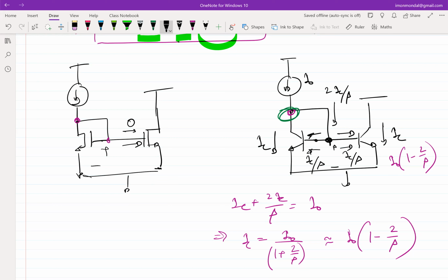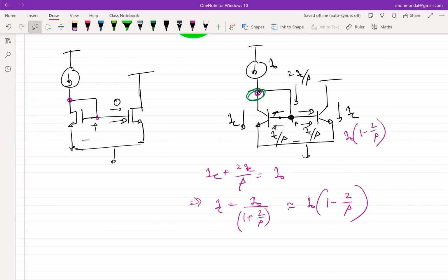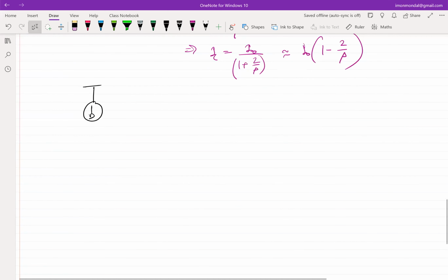Okay. So this is a problem, whatever I have shown here. Because of this problem, what is the solution? The solution is basically you have to put a voltage buffer between these two nodes so that you don't draw current, right? Input impedance should be high, output impedance should be low, and so on. And the simplest voltage buffer that we knew in case of a MOSFET was what? The common drain, source follower, right? So the same structure holds in this case. That's why in case of a BJT, the current mirrors are done in this way in most cases.